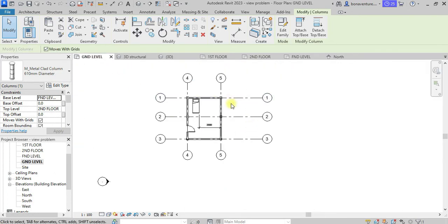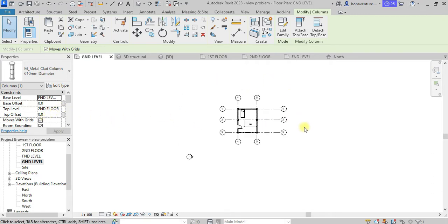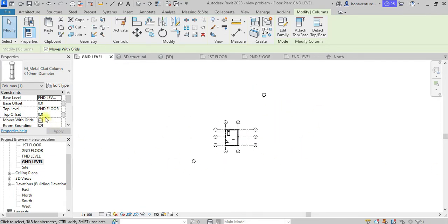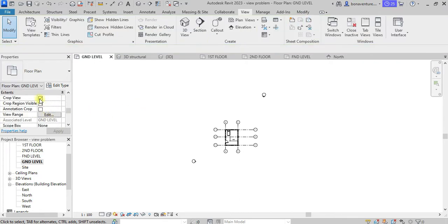The problem is not something too far-fetched. The problem could have been that maybe it has been cropped off. Now, for us to check, we can come to this, find where there is a crop region. Okay, this is it. So if you come under this crop region, you find out that it has been ticked. Crop region. See? So your problem is as a result of this crop.